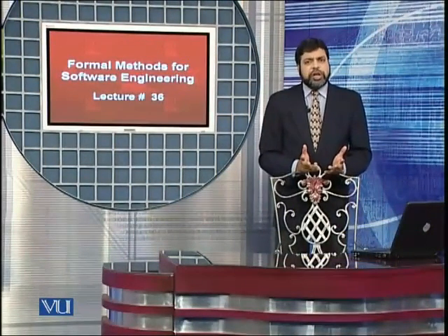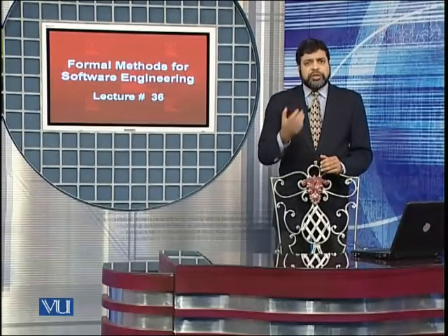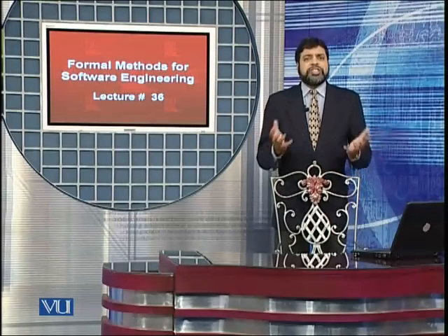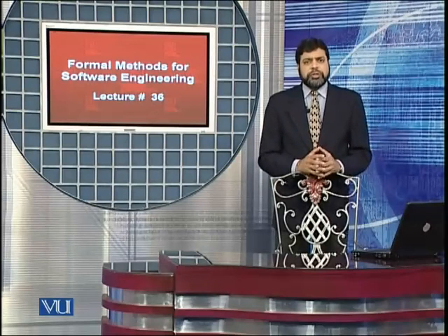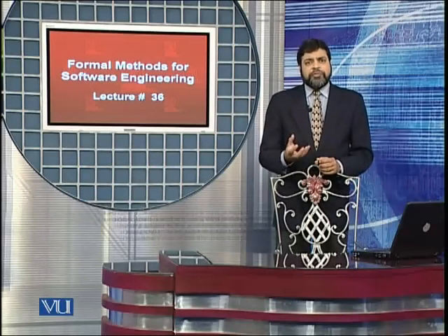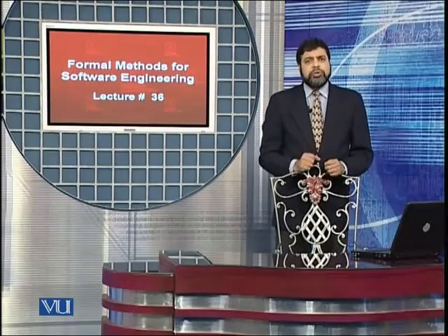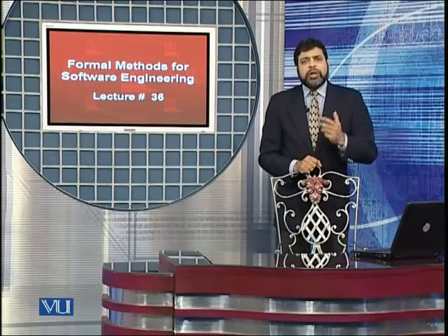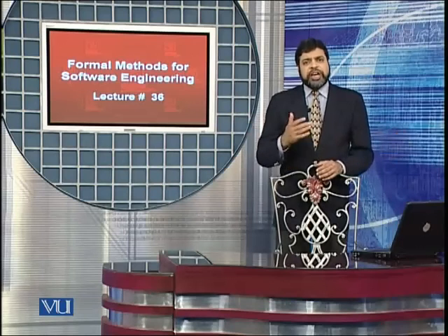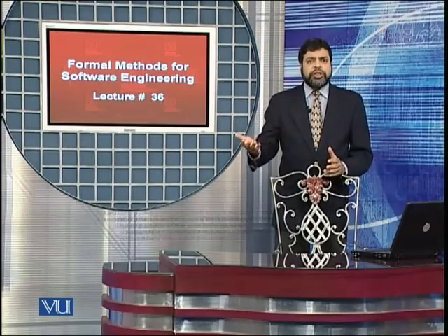The most important of these components obviously are the sensor that takes the reading and gives it to the controller. Controller is where all the decisions are made, all the instructions are sent to different components. For example, it will take the reading from the sensor and then it may send the pump the instruction to inject a certain amount of insulin into the body, and it may send messages to different displays showing the readings, showing the status, and so on and so forth.